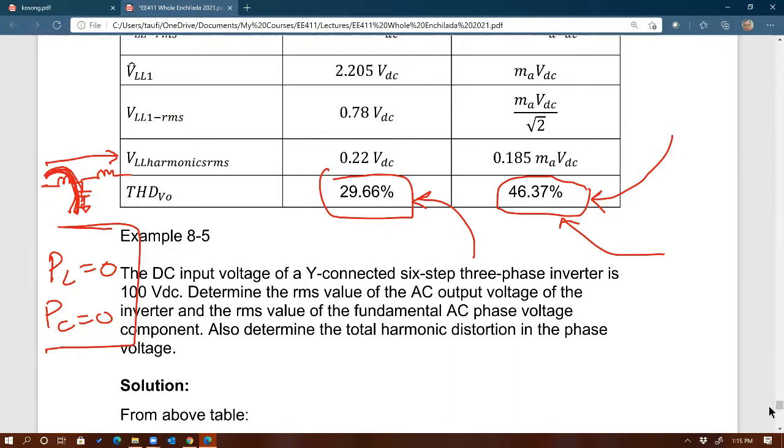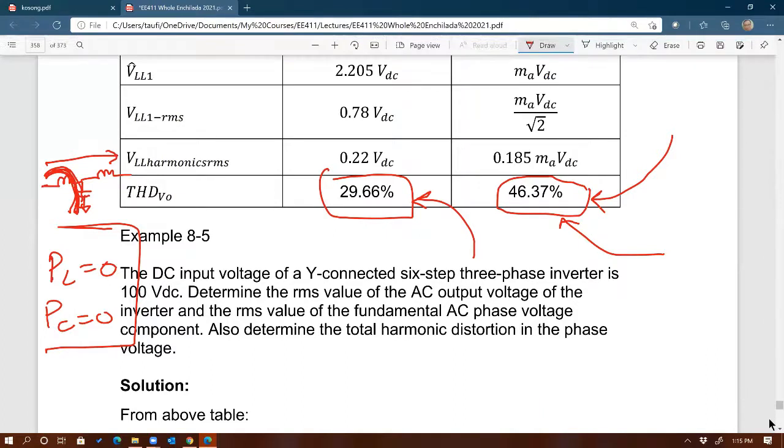We're going to lose some. Yeah, we're going to have ESR, we're going to have the DC resistance of the inductor, right? But still, it's going to be a lot lower than passing this energy into the load. Does that make sense? Yeah, because the load is going to be more primarily resistive than whatever LC network you have. Oh yeah. Okay. Yep. That makes sense. Okay. Thank you. That's just something I've been wondering in general. So thank you for clearing that up. Oh, you're welcome.